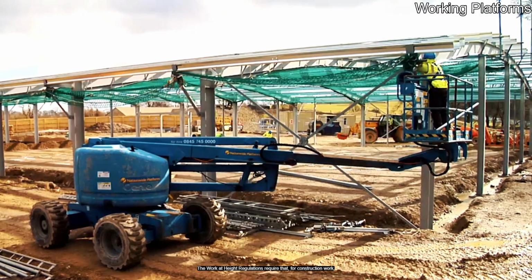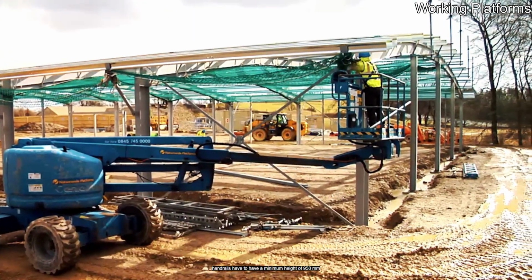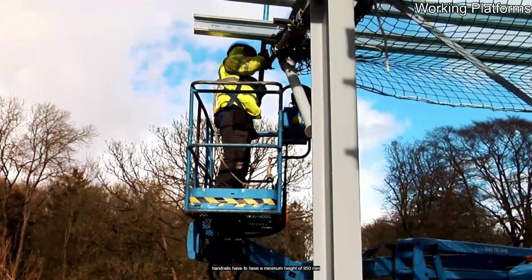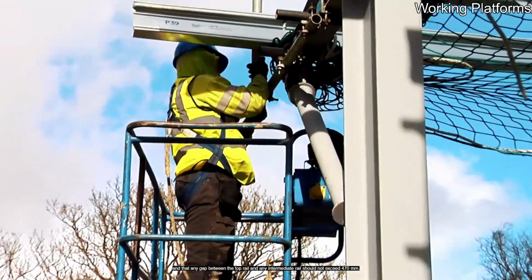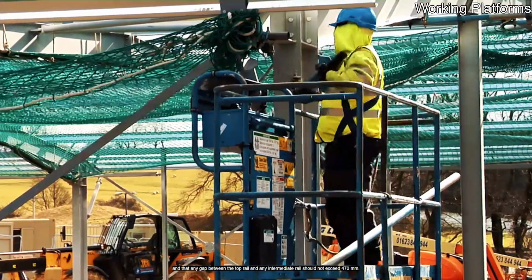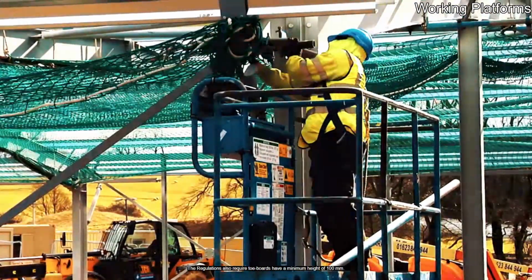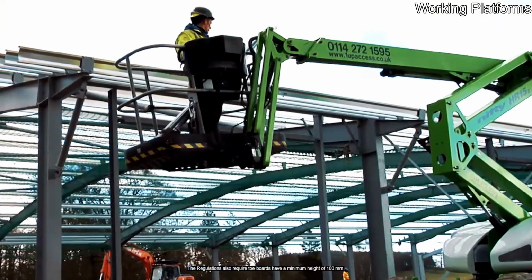The work at height regulations require that, for construction work, handrails have to have a minimum height of 950 mm, and that any gap between the top rail and any intermediate rail should not exceed 470 mm. The regulations also require toe boards have a minimum height of 100 mm.